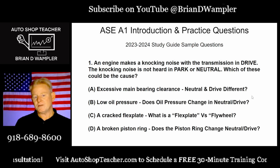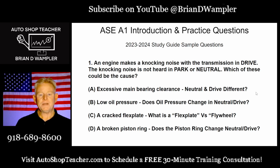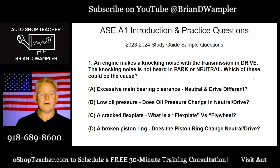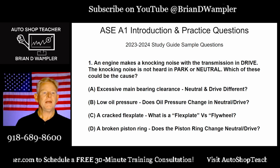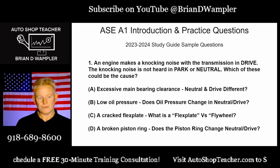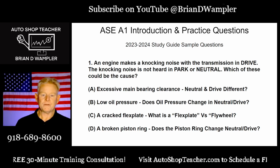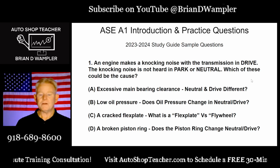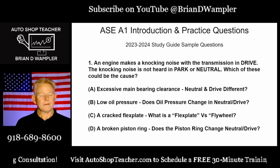On answer A, ask yourself, would excessive main bearing clearance be different in neutral or drive? Make sure you use all of the information provided in the question. It's not just a knocking noise, but a knocking noise in drive, with the additional information that it's not heard in park or neutral. So if we have excessive main bearing clearance, would it make a difference whether it's in neutral or drive? Same with low oil pressure. Dropping it into drive, is that going to change the oil pressure? Okay, think about your answers on this.